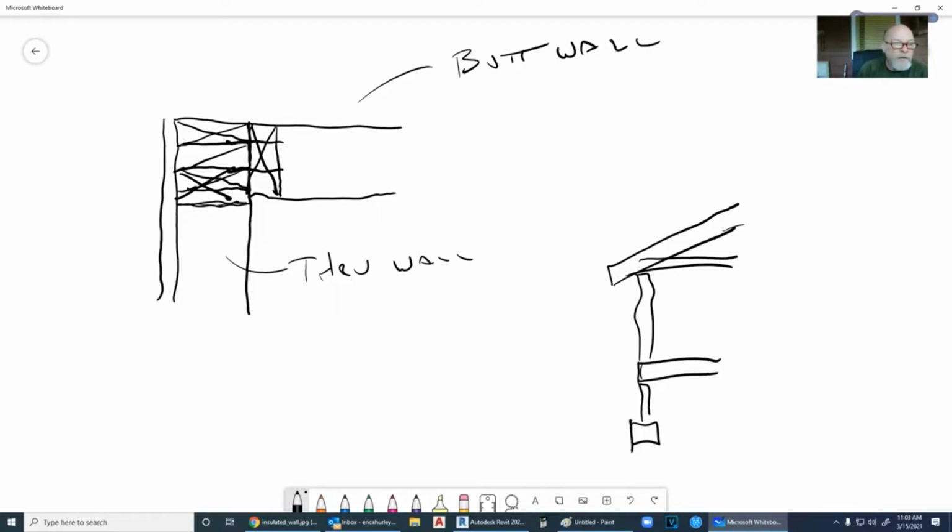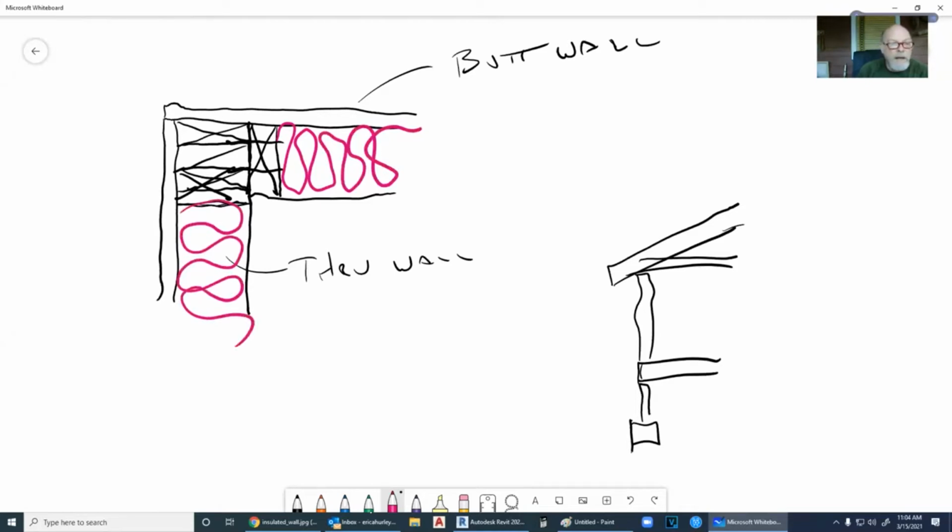So in the process, we put our plywood sheathing on here, and we've closed up this spot here. Then the insulation company comes in and they start putting insulation in the cavities. This little cavity here is covered on the outside and cannot be gotten to. So this is a huge open gap here in this wall.